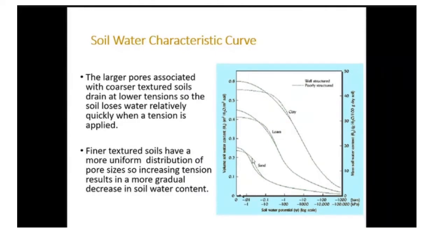And therefore, what happens is that it shows that with the increase of the pressure, the moisture content is reduced very much, because this kind of soil texture drains very quickly.